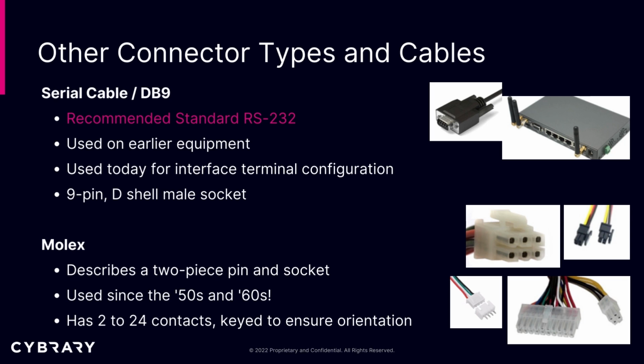Next we have the Molex connection. The Molex was a unique connection because it describes a two-piece pin and socket. You'll see these a lot on motherboards and other types of internal connections where it may have a series of plugs, but it has a unique pin and socket where the pins fit into a socket. They may be rated with 4 sockets, 6 sockets, even up to 24 contacts. And they're also keyed for unique orientation to ensure that the orientation stays correct.